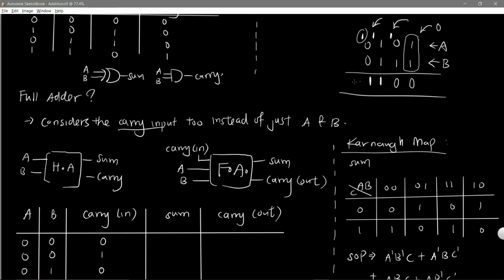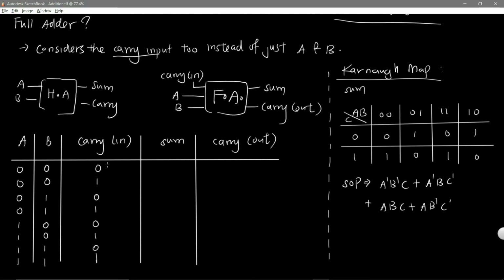So how do you design this? First, you must form the truth table. So when there are all zeros, you do not have any sum or carry. When only one of them is 1, you need a sum of 1 and 0 carry. Either of them 1, you have this combination. This here has only one 1 as well, so you have another combination of this. But if both are 1s, you have a combination of 0 sum and a carry, right? So if you have 2 1s, you have a 0 sum and a carry. And then 3 1s, you have 1 sum and 1 carry.